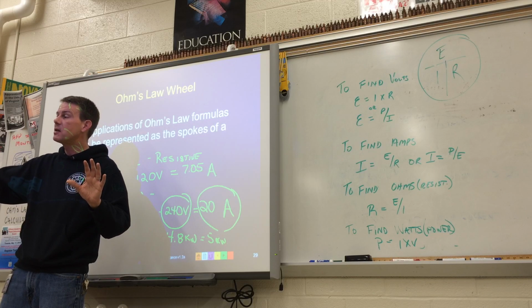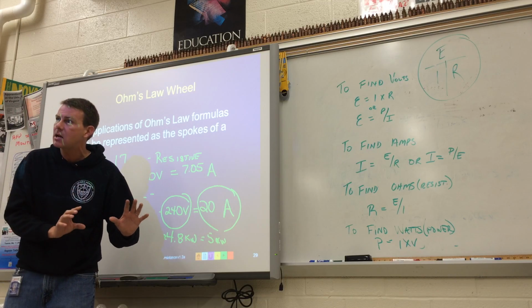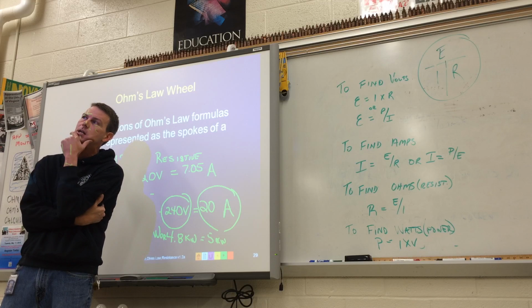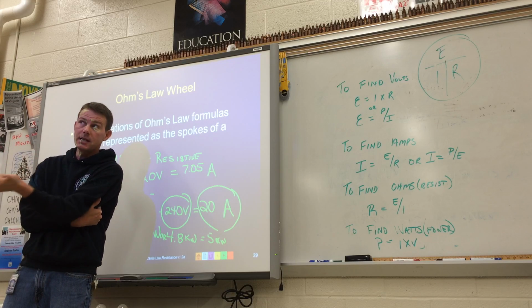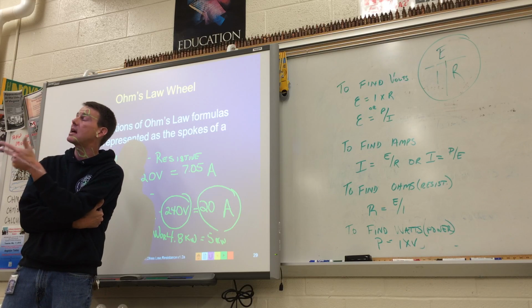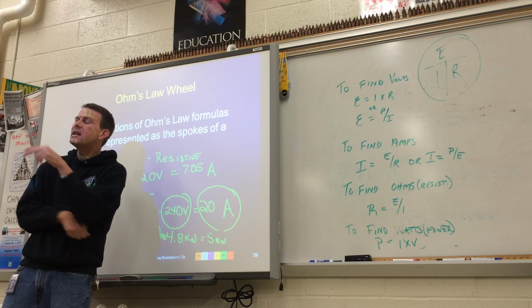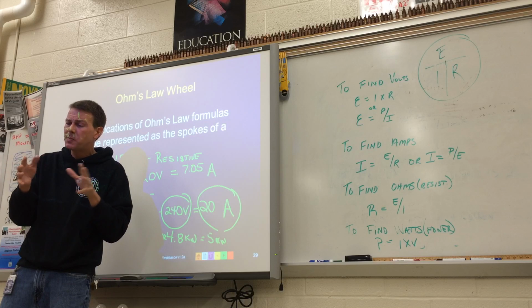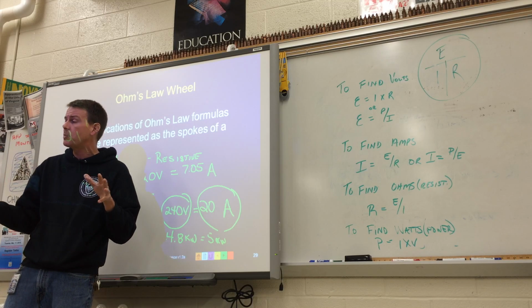And then there's another 20 amp circuit that's got to go around for all the counter plugs. What do you have plugged in on the counter? Tell me all the stuff that you think you have on a counter. Coffee maker, that's a big heating element. Toaster, that's another heating element. Dishwasher, that's another thing too. It's got a heating element and a pump for the water. A little mini oven, yep, one of the little toaster ovens, a little pizza oven, something like that. Blenders sometimes are on there, that's a motor too, pretty much the same thing.